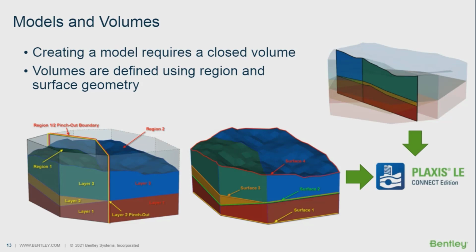So we can use this closed volume to proceed with the slope stability analysis, with the groundwater analysis, or even from the slice, we can then transition to the PLAXIS 2D. One of the other goals of creating the closed volume is also making sure that you don't have pinch outs in your model, in your final representation.